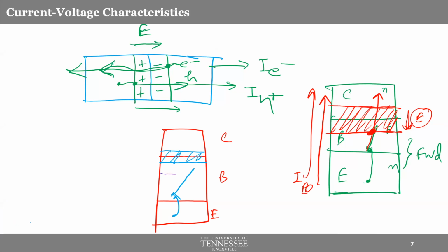if you have a thicker depletion layer like this, that means a more powerful reverse bias. Then the electrons should have already gone to the depletion layer, and they would have been grabbed by the electric field already, and they would have gone inside the collector. So the flow of electrons from emitter towards collector becomes easier if you have a stronger reverse bias in the base collector junction, right? Does that make sense?